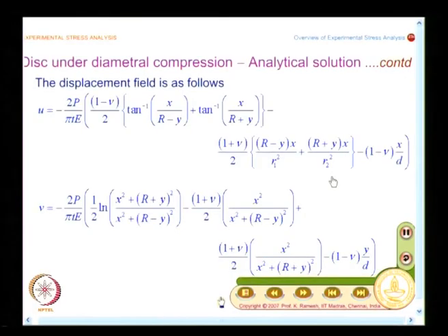On the other hand, I take the model, I put it in the appropriate optics, I get stress information, I get displacement information. The moment you want to go for strain, right now we do not have a technique which will give a whole field strain information. You can get from strain gauges and plot them, or from displacement information you can do numerical differentiation and plot the strain. But right now you do not have a whole field experimental technique which would give you whole field strain data conveniently.